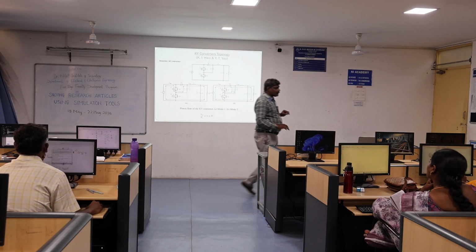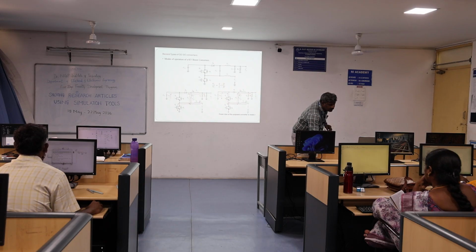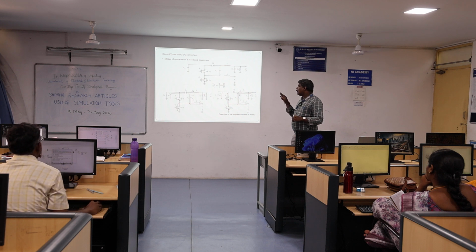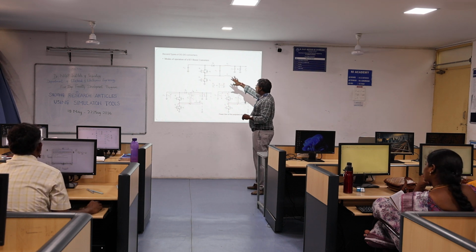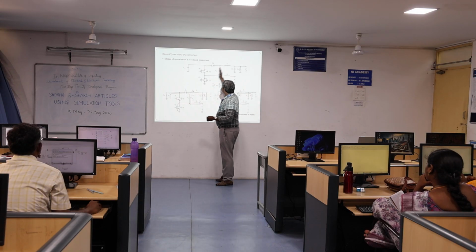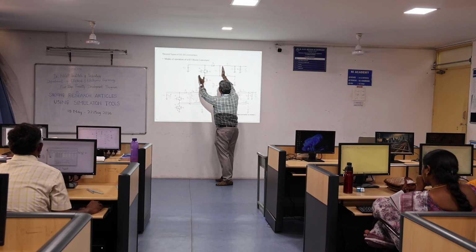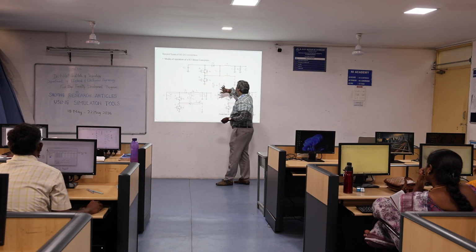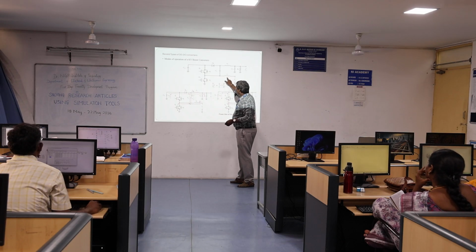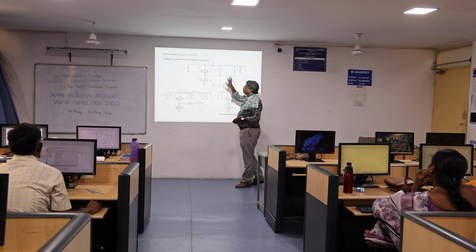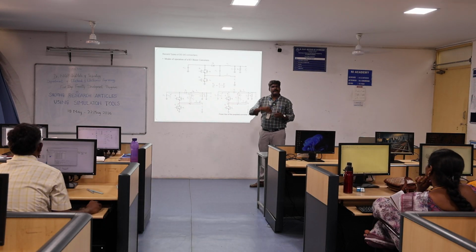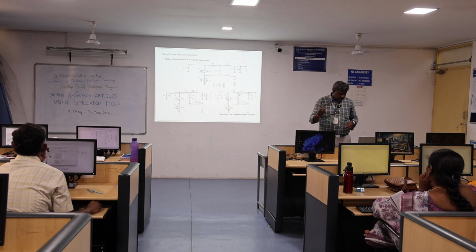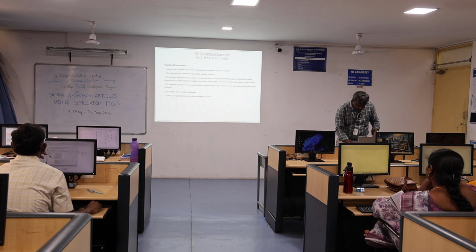So this is the basic fundamental circuit. Using this basic fundamental circuit, they add some components like an inductor, a capacitor and diode combinations, and now we have a KY boost converter. Just look at the previous circuit. This is the fundamental circuit, which needs two switches, a diode, and a capacitor and inductor combination. Just by adding this inductor and this capacitor, it is named the KY boost converter. Likewise they add some components, and based on that we name the KY boost converter, buck converter and buck-boost converter.